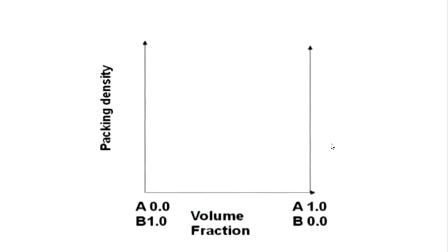Initially, when concrete is in the fresh state, it is able to flow. At that particular state, the density increases, and after some time when all the air voids or the disturbances and all the effects are getting over, it starts decreasing. So this is what happens initially in all states, but practically this curve represents the packing density. The red color is the theoretical value, whereas the black color represents the practical representation of packing density.